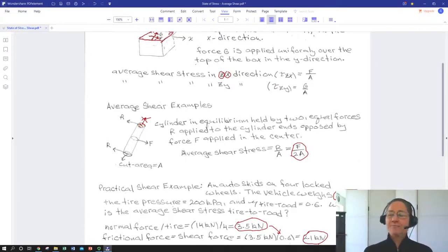So that's shear stress. So now we have two types of stress. Normal stress with a sigma, which is parallel to the surface normal and is generally viewed as being axial, perpendicular to a surface, and we have shear, where the force is parallel to the surface, perpendicular to the surface normal, and can go in either one of two orthogonal directions on any given surface.